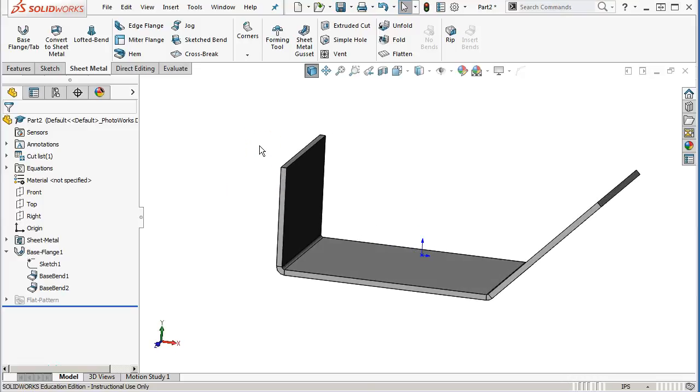So yes, we want to hit the final, but I'd almost say that if the tolerance on that flat pattern is an issue, that flat pattern needs to be redlined. If you say, I bent all of these not at 0.89 but at 0.91, and I got the desired result of the outside dimensions being the same, that needs to complete the cycle and go back to engineering. Otherwise, the information goes off the waterfall, flows downstream, never to be seen again. And then next time we do it, they get the same drawing, they do the same things.